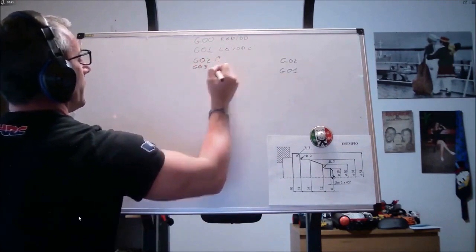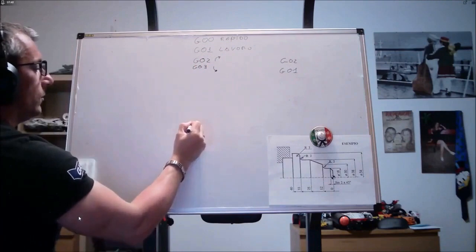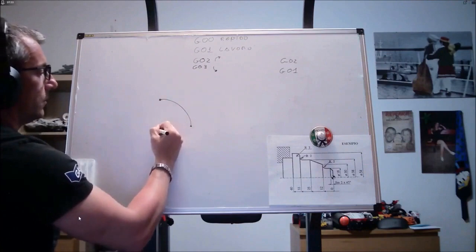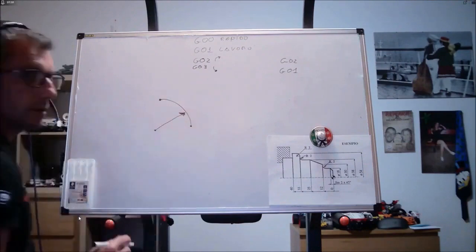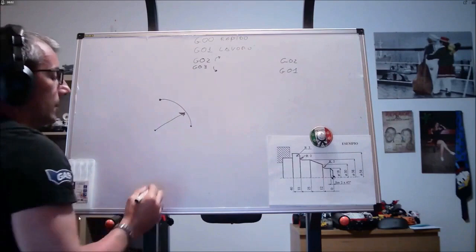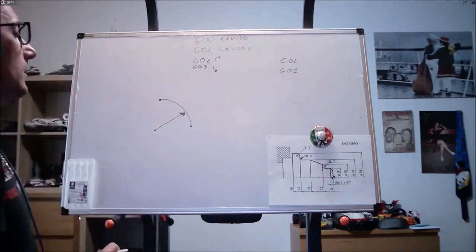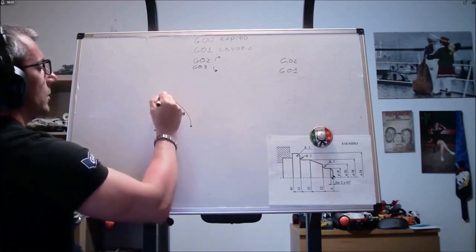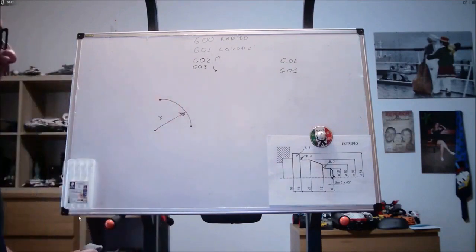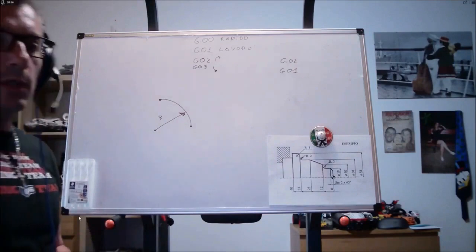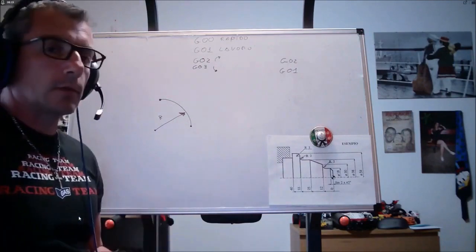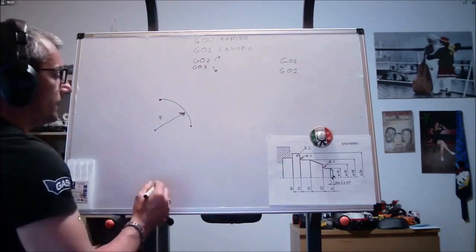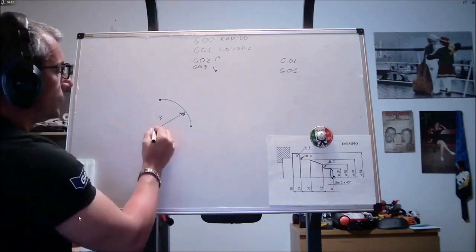What are these things? They are the starting point, the ending point, and either the center or the radius. Putting in 4 would already be a problem. So, ultimately, we are quite lucky because CNC programmers have understood that when I provide a starting point and an ending point, I only need to give a radius, and there will be only one and only one circle passing through these 2 points. Then the center point was required.